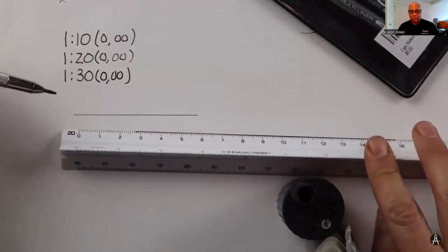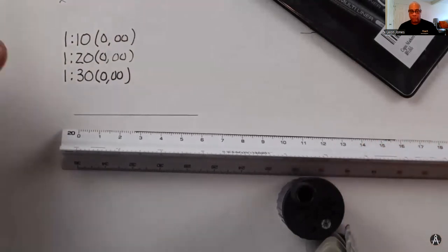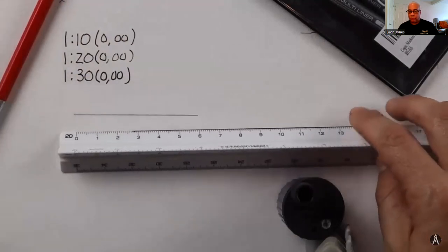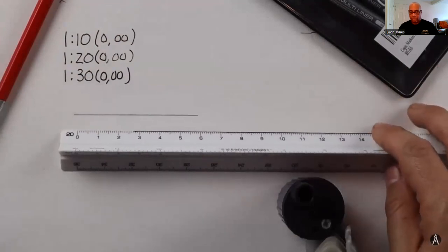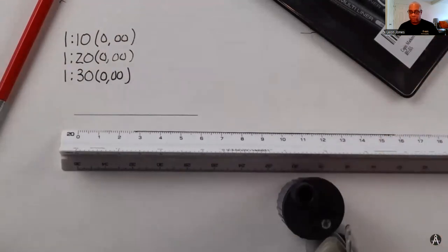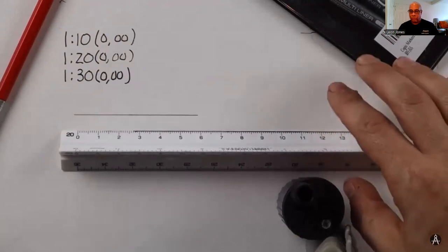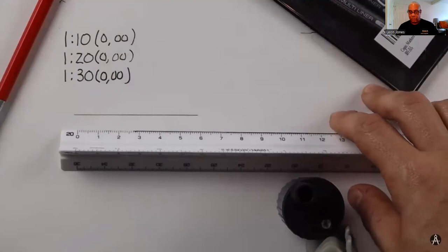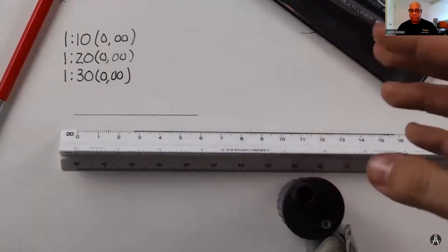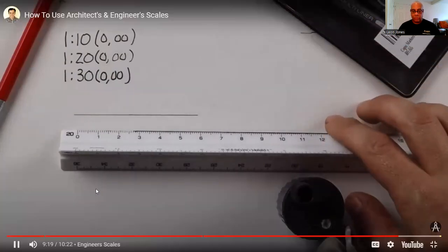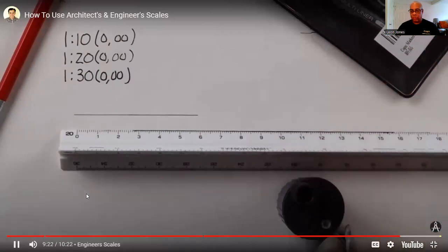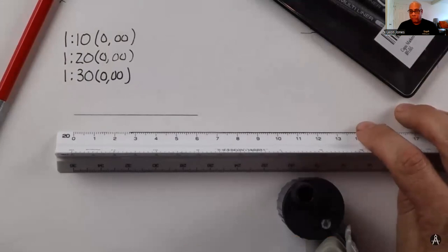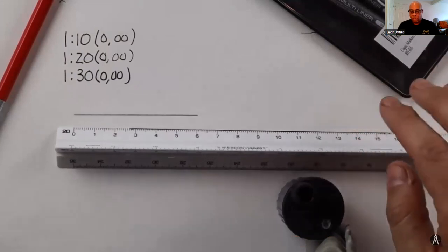So you can see using the engineer scale or the architect scales is quite simple, quite easy. Doesn't take that long to use. You can draw and measure lines with both. As you practice, you'll find preference with either one. For most landscape architects, you're going to be using mostly the engineer scales for larger plans. For landscape designers, for residential properties, you'll primarily use an architect scale probably, but they're very interchangeable. So do make sure that you get comfortable using both. Again, they're very valuable tools.